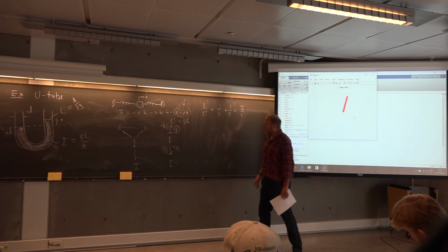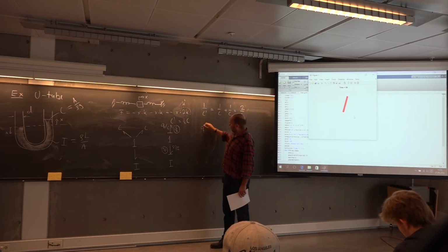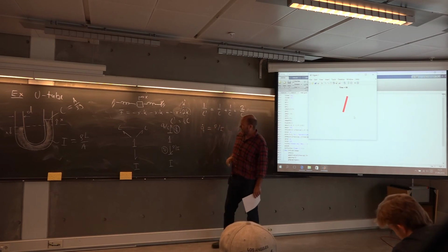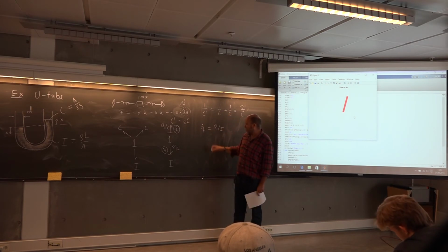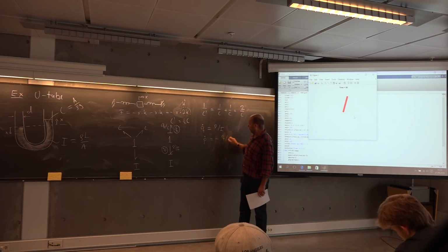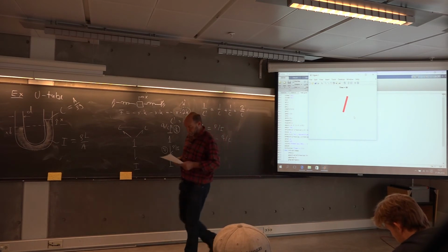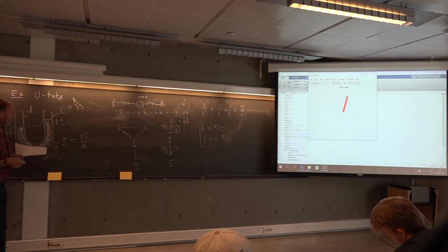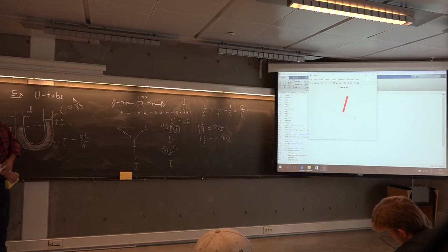And our equations: one junction, common flow, Q dot equals P over I. While these two, they have to be added together to get 0, hence P dot equals minus Q over C. So there you have your 2 first order equations. Everybody agrees on that?